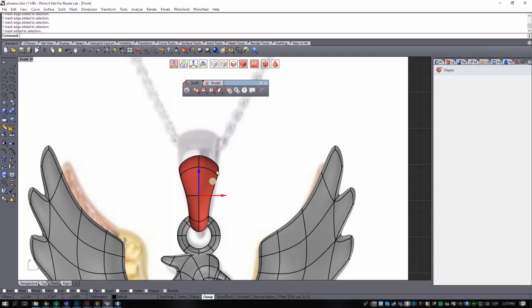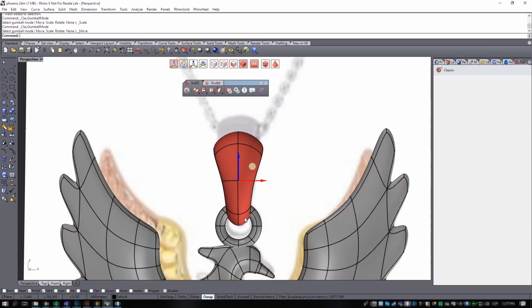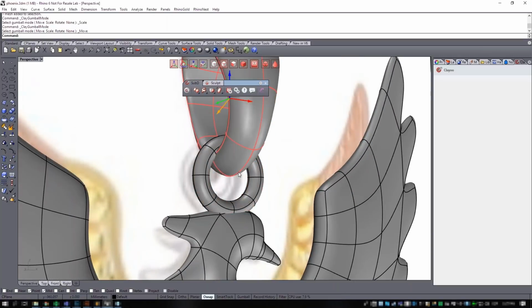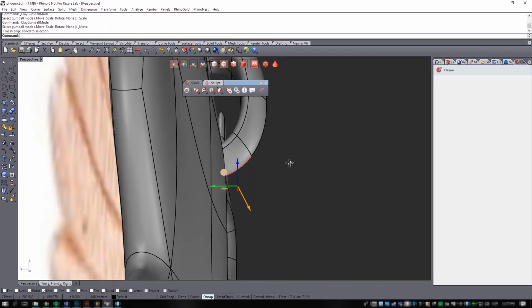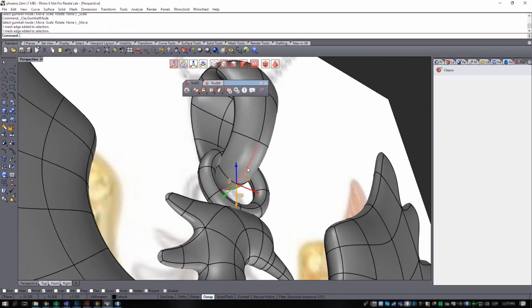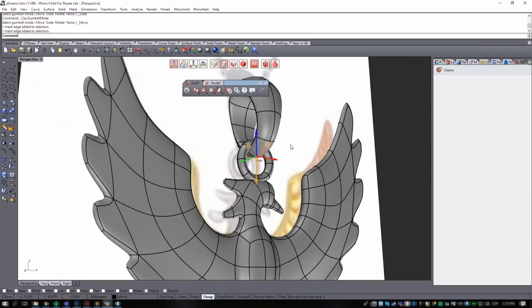If from the front view we need it a little bit bigger, or a little bit stretched, we can do it easily. Okay, so just select, click R, scale it a little bit, okay, and move it up just to make sure that it matches perfectly. If I don't need so much thickness on the bottom part, we can always select these edges on the bottom part, okay, and move them up a little bit.